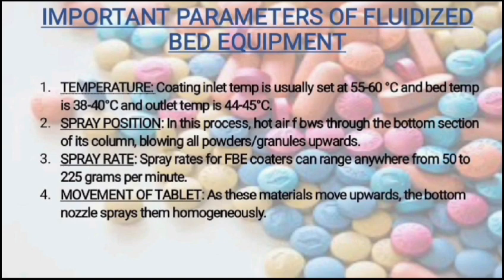And the spray position we use in this process is bottom spray. And the rate of spray is 50 to 225 gram per minute. And the last we have is the movement of tablets, which should be in an upward direction because we use bottom spray.